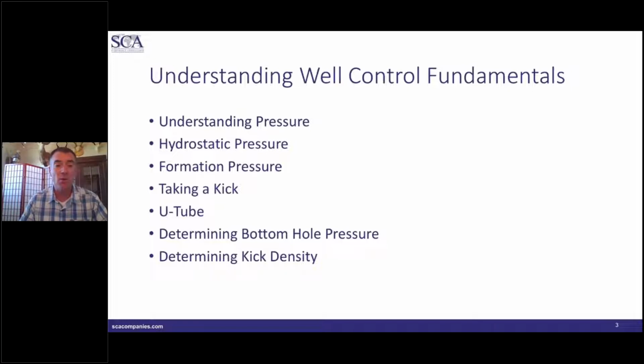We'll talk about what happens while we're taking a kick and what the pressures look like, and how they form in our wellbore. We'll talk about how the wellbore becomes a U-tube, and you'll see what I mean going forward. Then we'll determine bottom hole pressure, and from that we'll be able to determine kick density to a relatively high level of precision, good enough to know what you're dealing with.